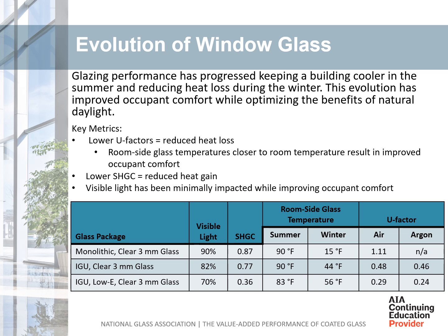As an example, we have progressed from monolithic to dual pane and coated glass, with data highlighting light to solar gain ratio with respect to visible light and solar heat gain. U factor insulation improves respectively from monolithic uncoated to low-E IGU with gas fill.